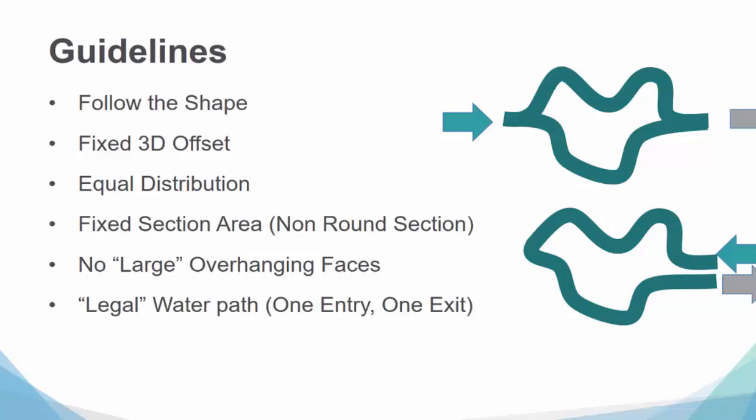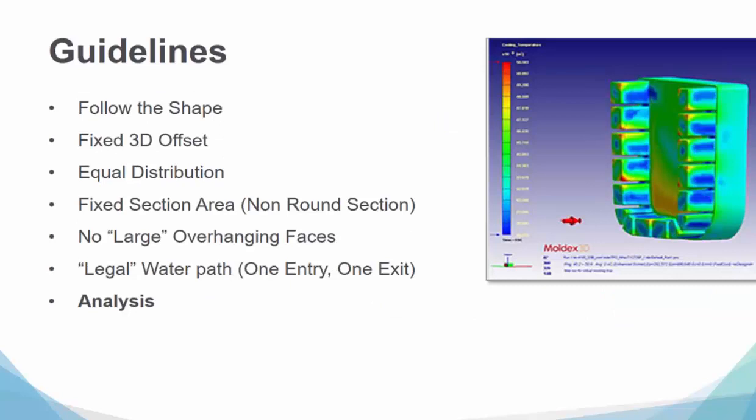That's a nice starting point that you can use, and stick to those rules as you start building your water lines. And with that comes the importance of being able to analyze what you've done. So now you can tweak it. Now maybe if you do move them closer together, you'll get more heat drawn away from the part.